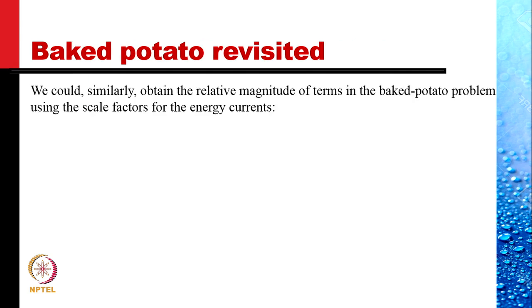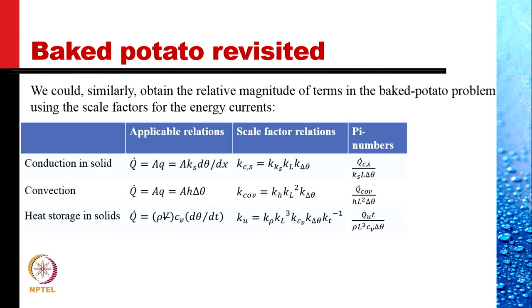We could similarly obtain the relative magnitudes of the terms in the baked potato problem using the scale factors for the energy currents. The three energy currents that are important are conduction in solid, convection, and heat storage in solids. The applicable relation: Q dot is area times the conductive heat flux, so it is area times Ks d theta by dx.